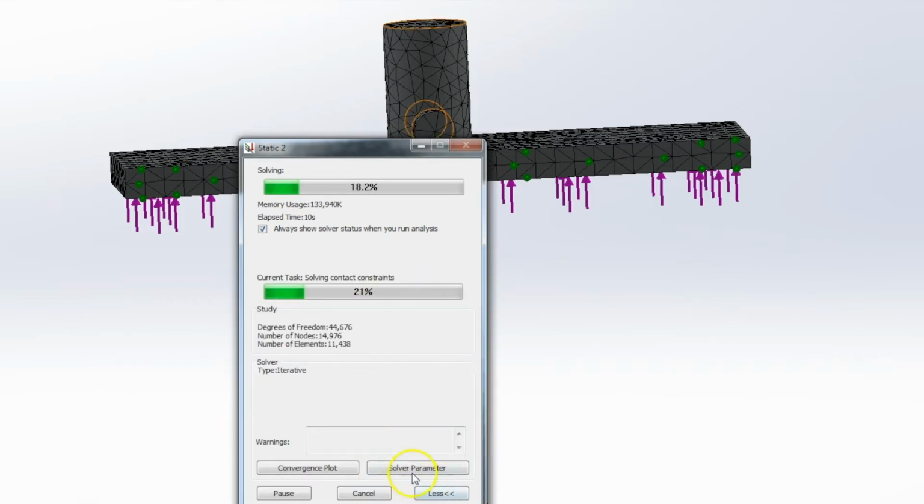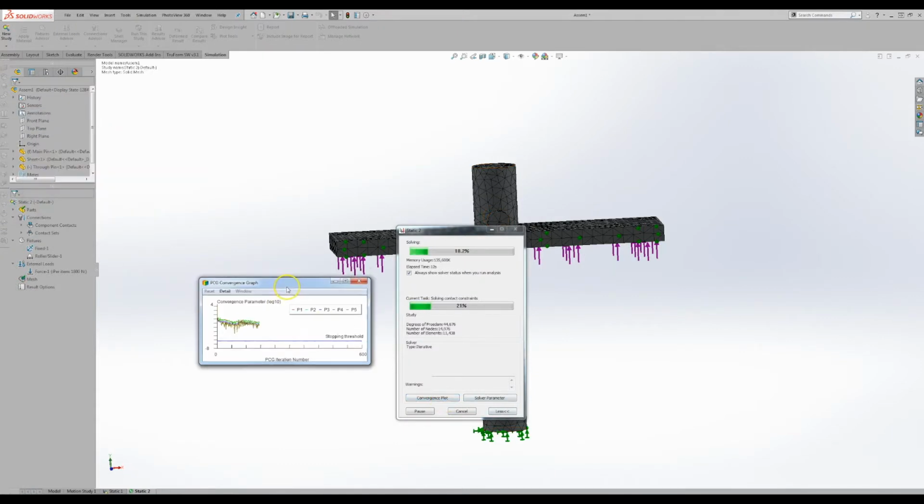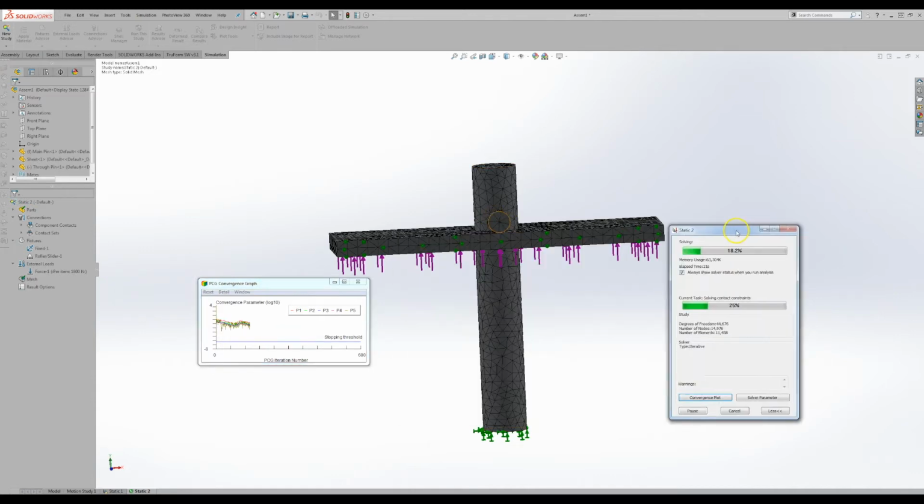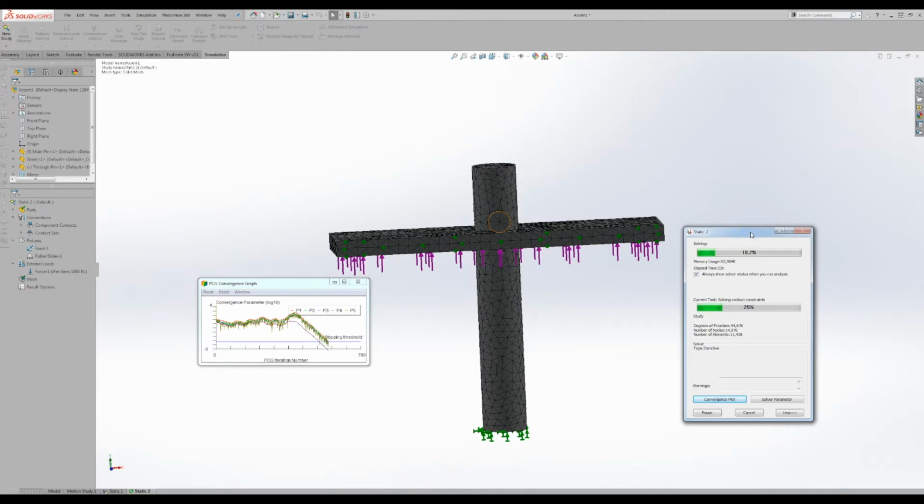Now this next little trick is something that I learned on a support call with my CAD reseller. Sometimes you'll be running the simulation and you'll just get these static green bars and you'll think, what's happening here? Has the thing frozen? So if you hit on the convergence plot, you can actually have some amount of faith that the computer is crunching through the values, and no doubt this will show to someone much more intelligent than me some useful information.